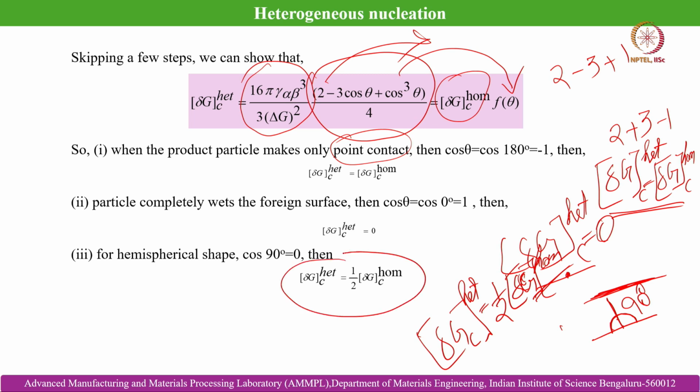we are trying to achieve. So, how can we achieve it? We can promote heterogeneous nucleation within the solidifying melt by incorporating some external seed particles, for example grain refiner or modifying agents, within the solidifying melt, so that they can facilitate decreasing the nucleation barrier, and we can get a lesser nucleation barrier and higher nucleation of primary grain, primary solid within the liquid melt.